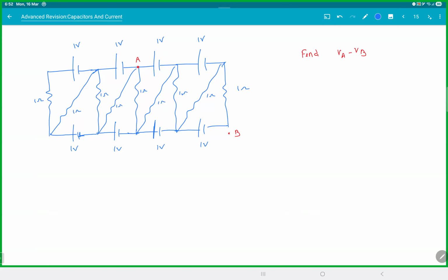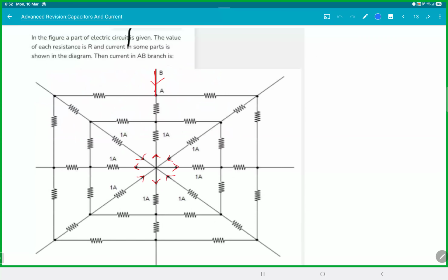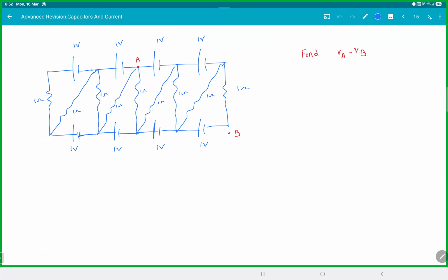So circuits, right? There are two ways to solve. One is Kirchhoff's junction law and one is Kirchhoff's loop law. Between these two, Kirchhoff's junction law is more preferable. It is faster. It will always give you one equation less, saves you time, and is kind of safer if you ask me. The Kirchhoff's loop law is good when you're playing with something like these maze circuits, when you literally have to travel around. Or when you have an inductor, capacitor, resistor, all mixed, generally the loop law is good. So how do we start this thing?